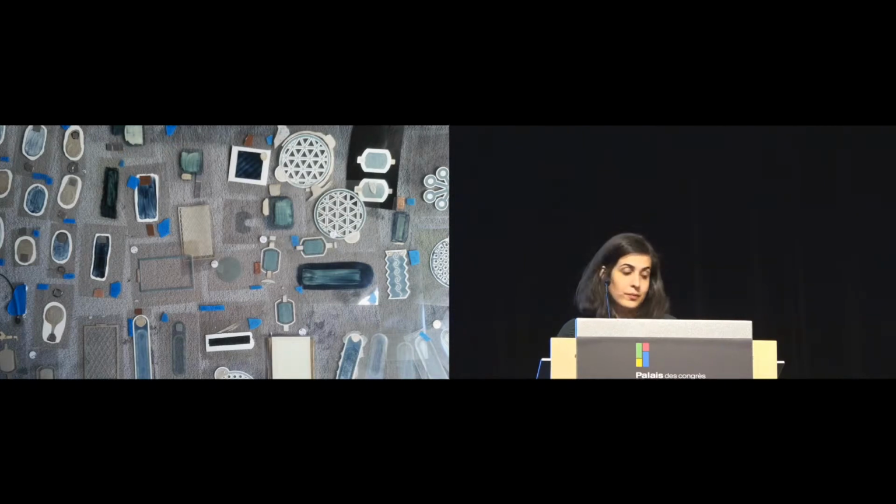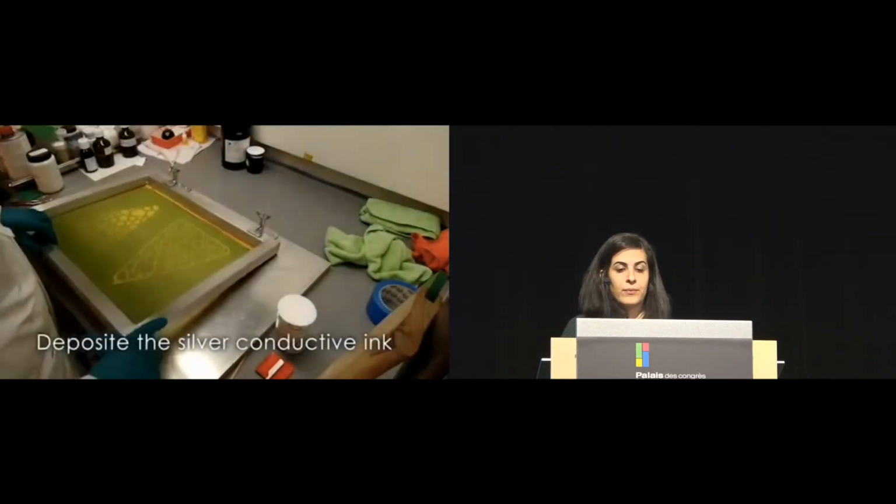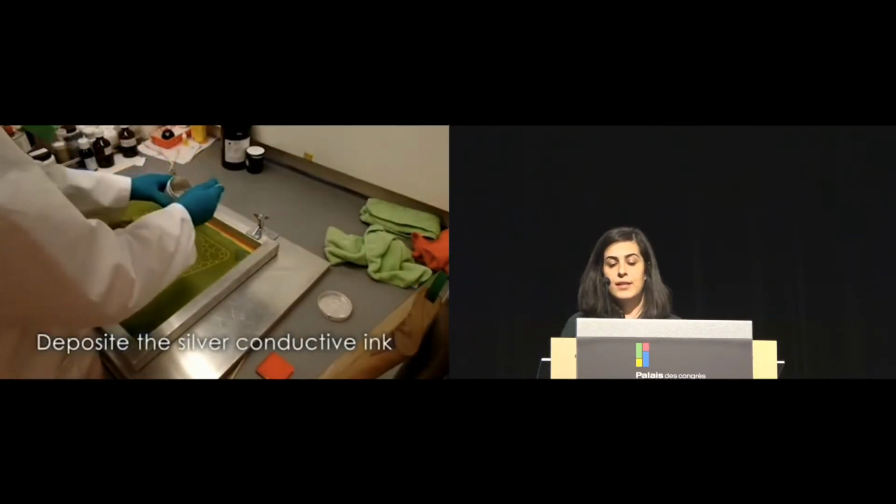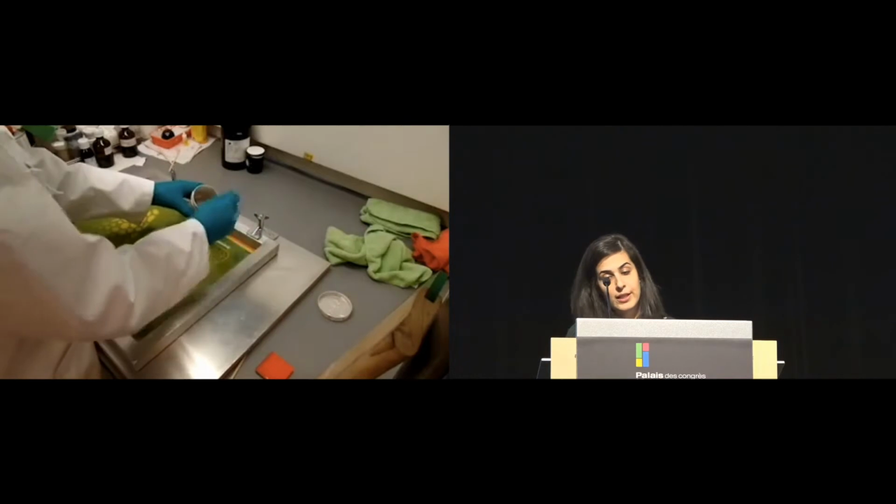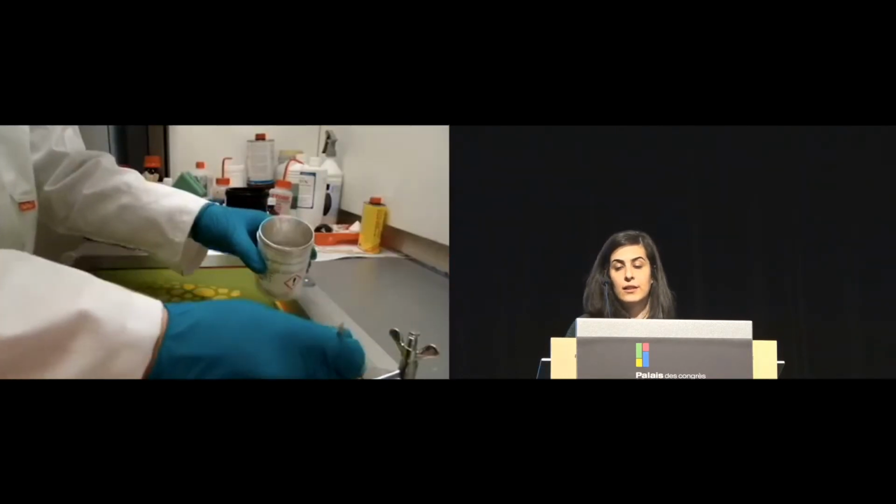Electroluminescent material samples, which I have many here, and please feel welcome to come and visit them, are composed of 5 components: a substrate, which can be transparent or non-transparent, conductive or non-conductive, 2 conductors, at least one of which must be transparent to let the light go out, and phosphor and dielectric insulator, which are sandwiched between the 2 conductors. Here you see a video in which my student, Stanklas, is screen printing and curing a layer of silver conductor.